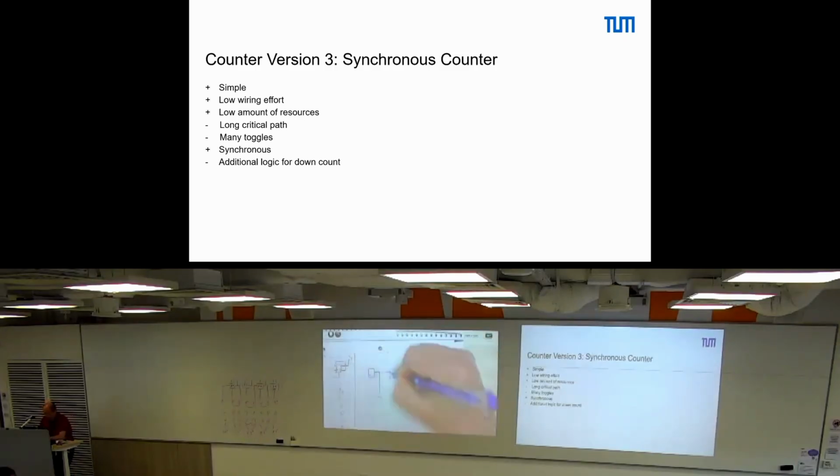And then we put the event to all of these flip-flops in parallel. Of course, all of this also needs an initialization. I just skipped the initialization. And the input to the first flip-flop should be some feedback, which goes again from Q bar.